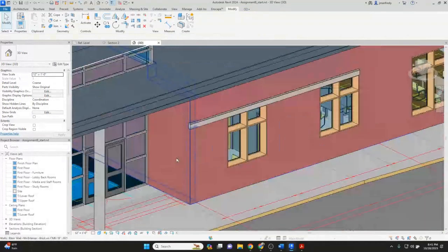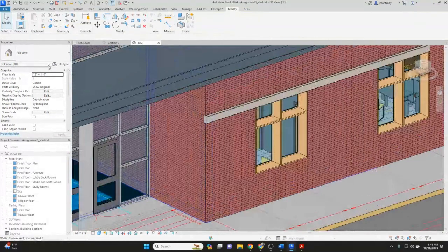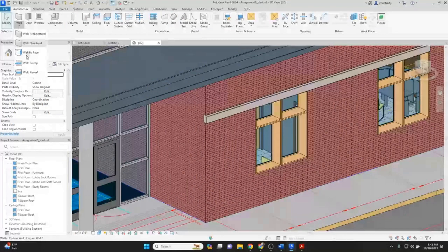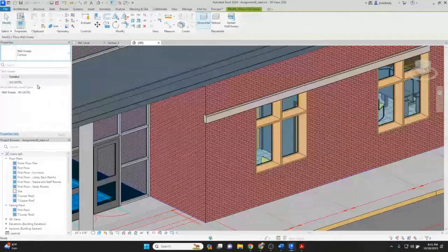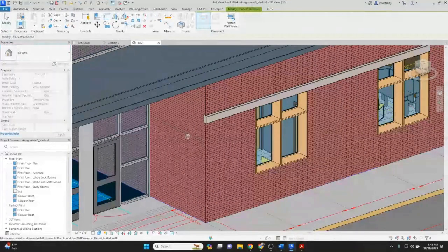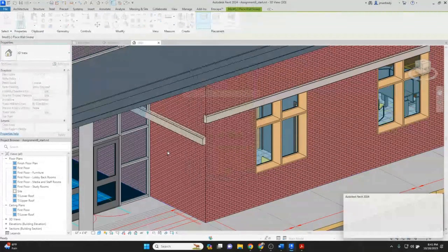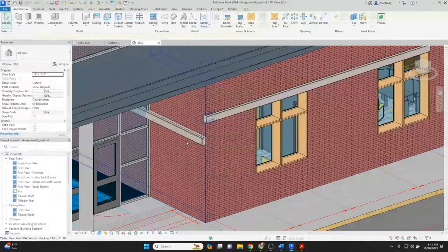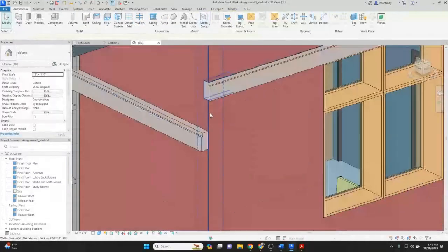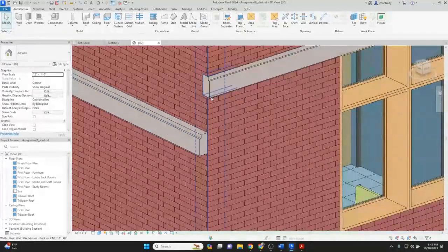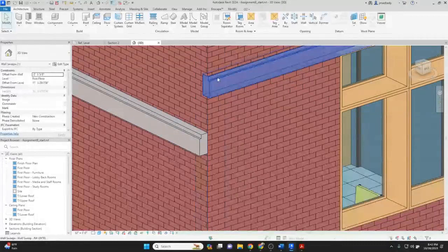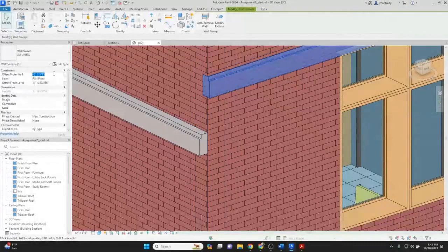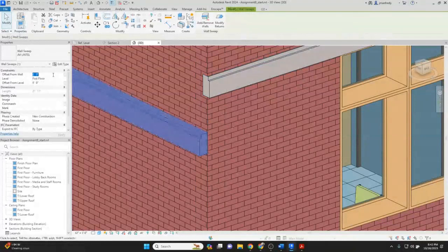This object here can also be across the side here, so I can basically make another wall sweep called John's Lintel and place it here. It disappears until you hit enter. Then it shows up here. I suggest you line them up. So take the bottom of this and line up with the bottom of that. And you probably want them to be recessed in the same dimension. So this is -3 5/8. Click on this one. Use the same number for the offset, -3 5/8. So now they're both in the same place.